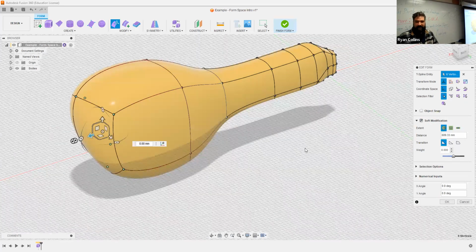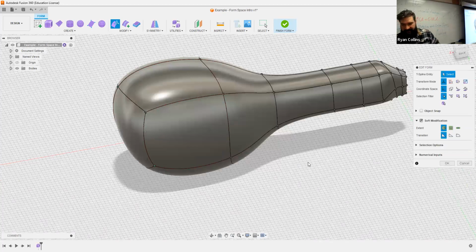Select the checkbox. Let me change off of the color view to appearance view because it's gray. So Shift N, and it's gray, so you can see the lines appear a little bit more effectively. Right now, I don't have anything selected. All right, nothing's there. You have some options. The extent means the distance that it is effective at, or rather, your selection. Distance means actual linear effectiveness. Face count is by faces, how far away the faces are. And then rectangular face count is just kind of straight across.